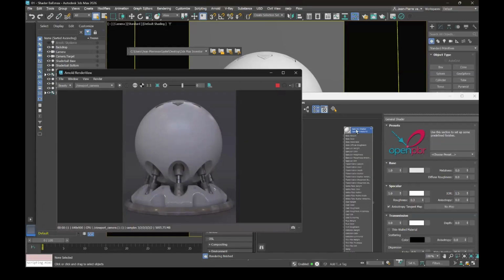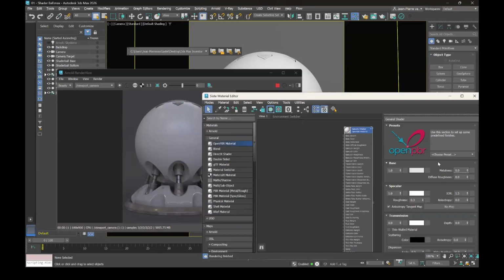And the cool thing is, if I start playing with some basic parameters like metalness, so if I want to create this material as a metal, I only need to set the switch to 1. And now, ta-da, it looks like a metal. And I still have some blurry reflections, and that's due to the roughness. Every material obviously has some roughness, but now it's set to 30%.